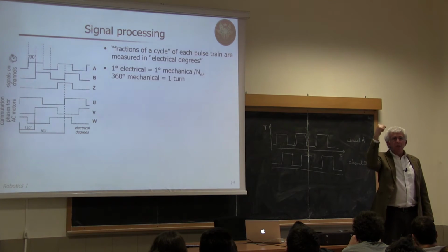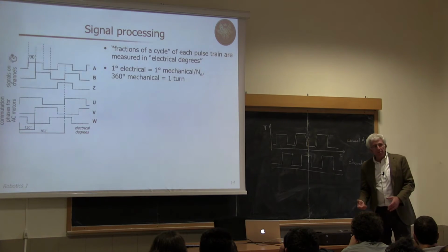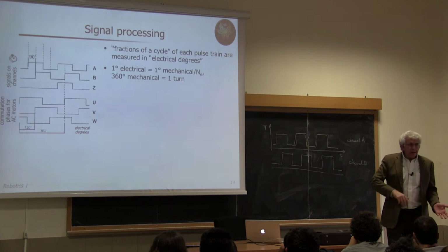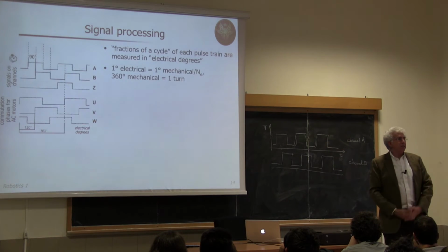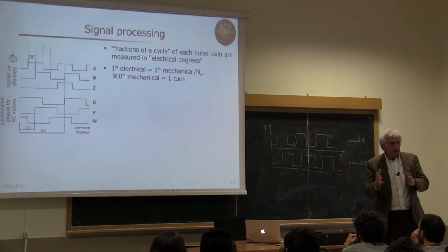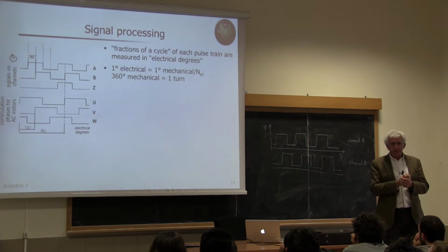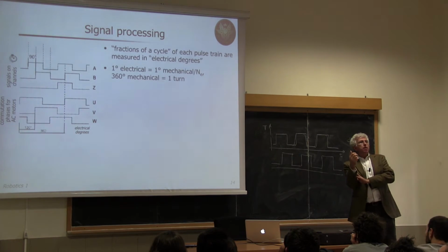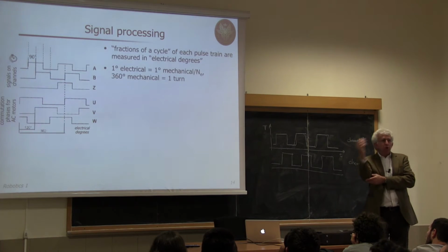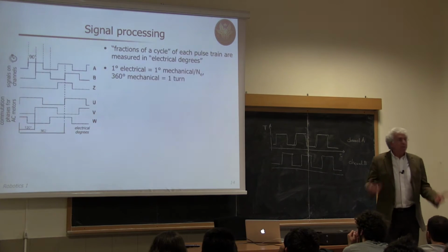So you will see one joint moving in one direction and then in the other direction, okay, till it finds some reference point, some mechanical stop, and then the first time it encounters the Z track, it zeroes the counting. Okay, from there on, it knows how the link is placed. And then it moves to the before last link that is being moved around its driving joint, and it repeats the same procedure.